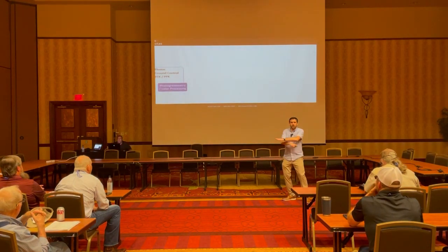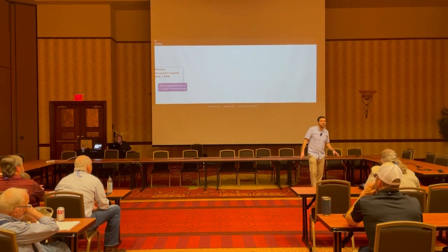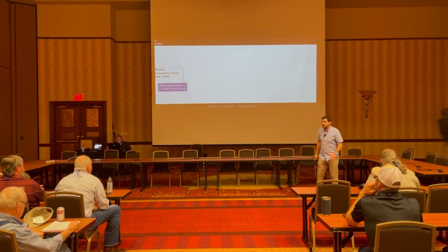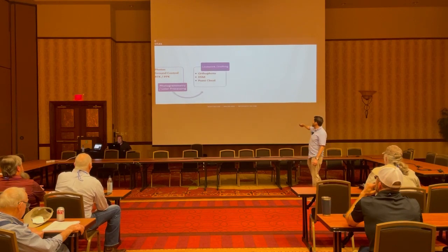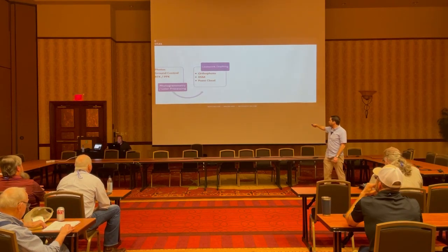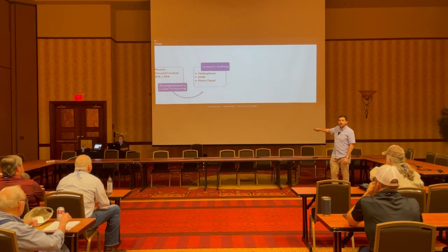So just to kind of summarize what this process looks like before we start digging into the detail of each individual step, because this workflow is fairly important. So you start with photos, ground control data, and GPS data, RTK or PPK. That goes through the photogrammetry and LiDAR processing step. What that spits out is an orthophoto, a DSM or digital surface model, and a point cloud.